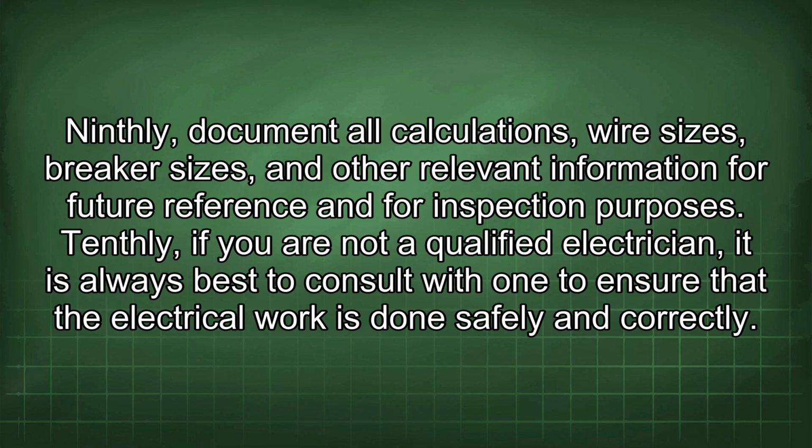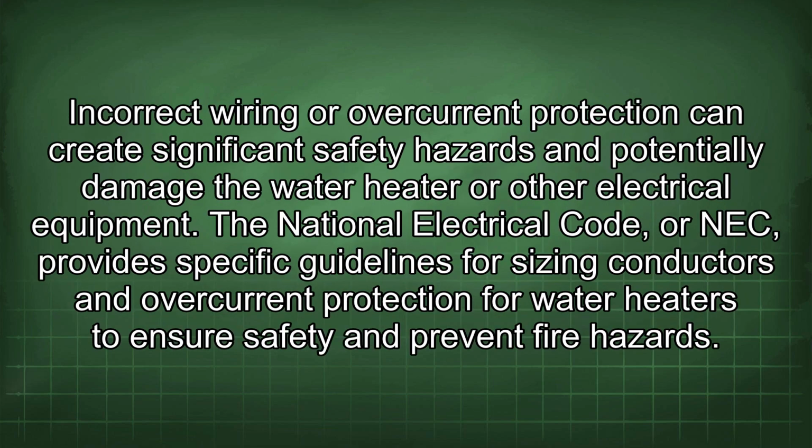Tenthly, if you are not a qualified electrician, it is always best to consult with one to ensure that the electrical work is done safely and correctly. Incorrect wiring or overcurrent protection can create significant safety hazards and potentially damage the water heater or other electrical equipment. The National Electrical Code, or NEC, provides specific guidelines for sizing conductors and overcurrent protection for water heaters to ensure safety and prevent fire hazards.